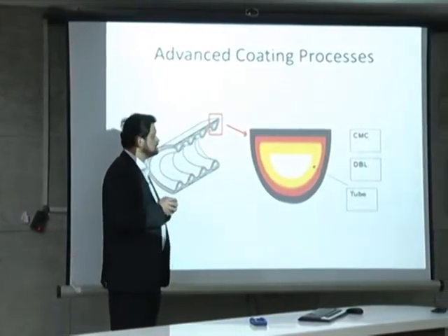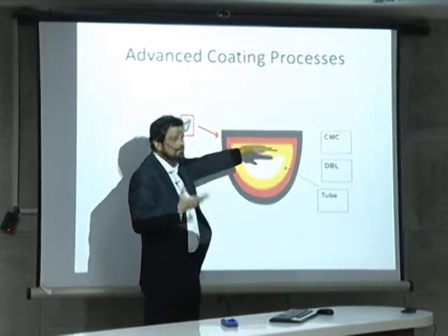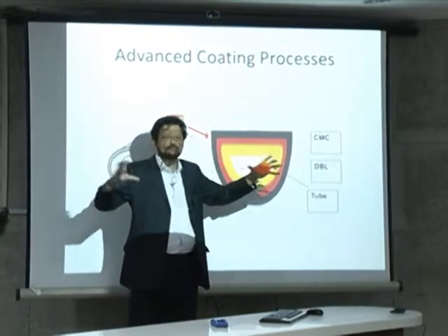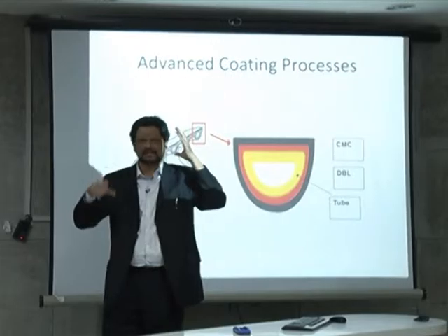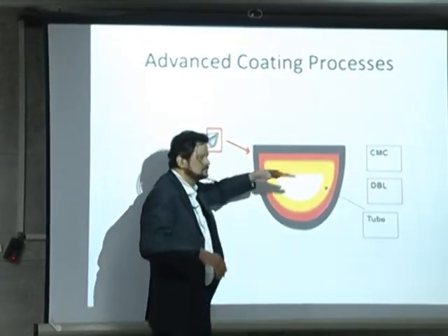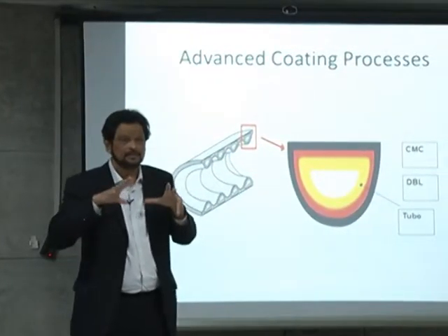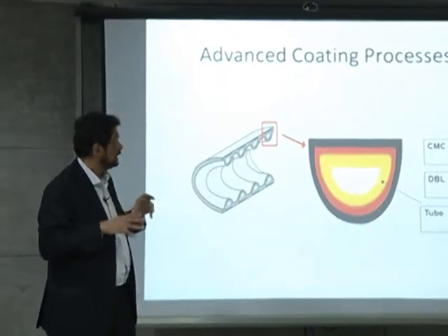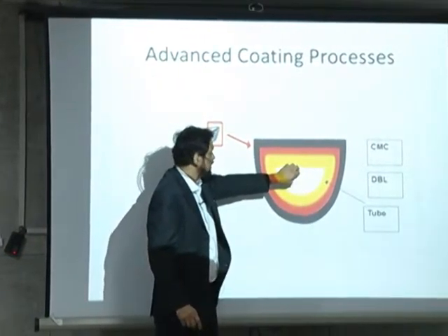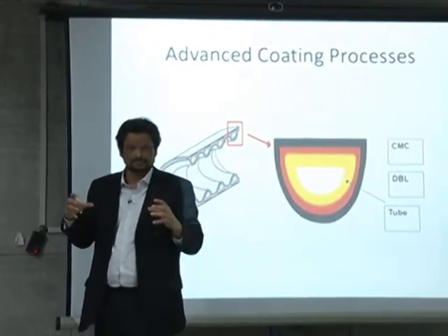Now the problem is, and there are multiple problems, at very high temperature the ceramic will start, let's say we make a tube of some material, some rhenium, titanium, whatever metal. The ceramic starts dissolving literally into the tube. At the same time, the inside fluid starts corroding the tube surface.